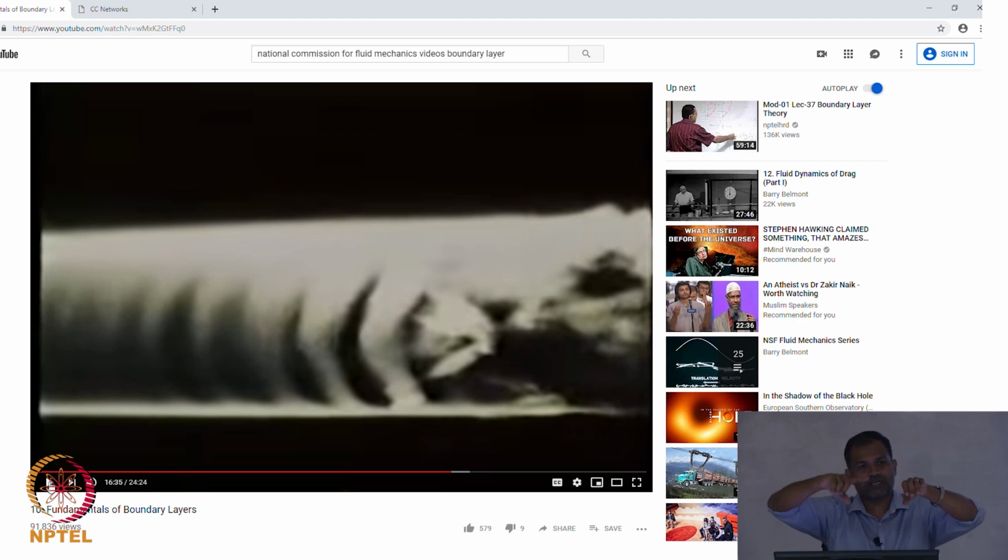It's a round thing, and therefore a boundary layer grows on top of the pipe, and there they have characterized it. On the leftmost you have a laminar boundary layer, and then what you see is some kind of waves and so on, that essentially represents transition, and here much further downstream it basically turns into turbulent boundary layer.